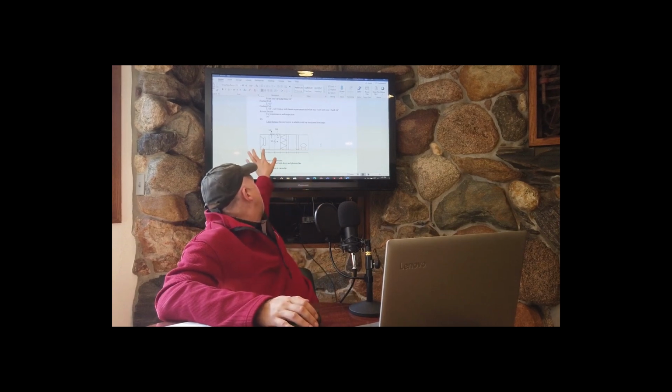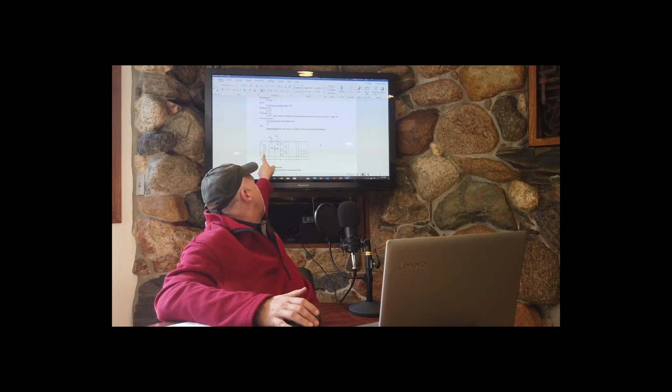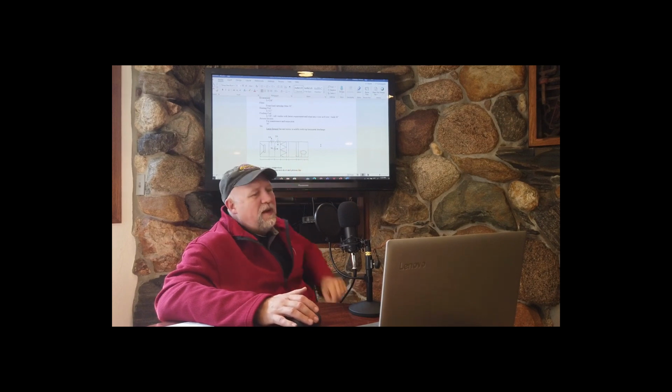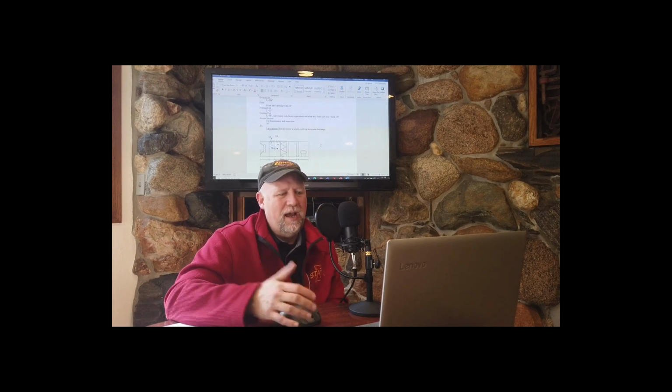Let me just, for you to label the various parts, this is a return air fan. This is an economizer section, the whole thing here. This is a filter section. This is a heating coil. This is an access section. This is a cooling coil, and this is a supply fan section. That is the minimum parts that I want you to have.